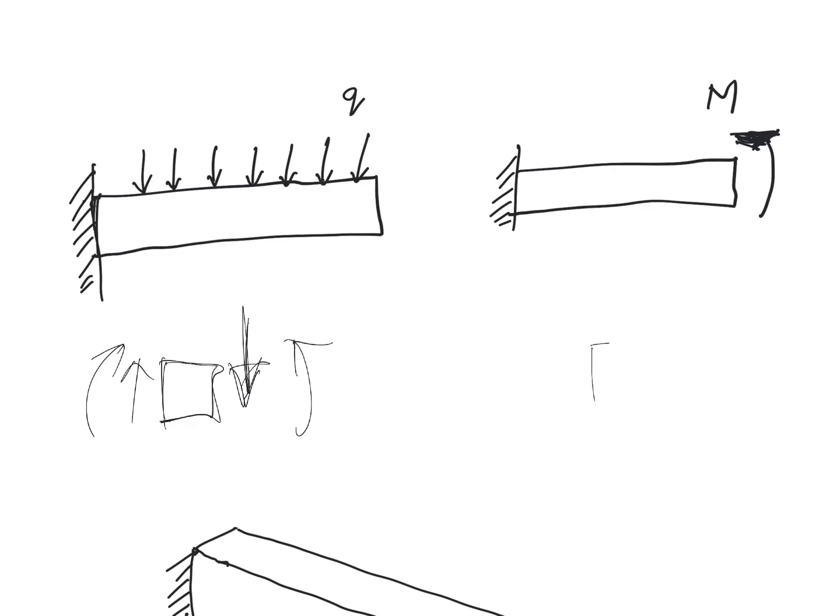Now if I do a similar exercise for case two, I will end up with a free body diagram something like this. So in case two, the element is subjected to pure bending, just the bending moment alone. And in case one, you have both shear forces as well as bending moment. Always keep in mind that Euler-Bernoulli theory, and this particular formula, were derived assuming that the element is in pure bending. So in case one, it is not that accurate, but the amount of error is not that much, which I will tell you in a while. So it is more applicable in case two.